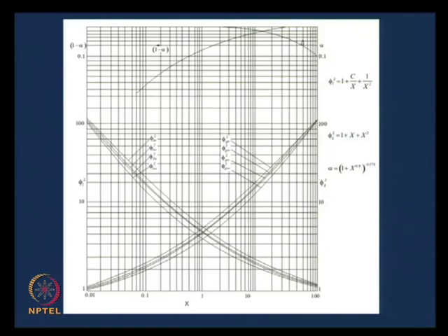So, from this one curve, if you can calculate x square, you can calculate phi L square, you can calculate alpha. Moment you can calculate both these quantities, we can go to the mixture momentum equation which we had derived for 2 phase separated flow.